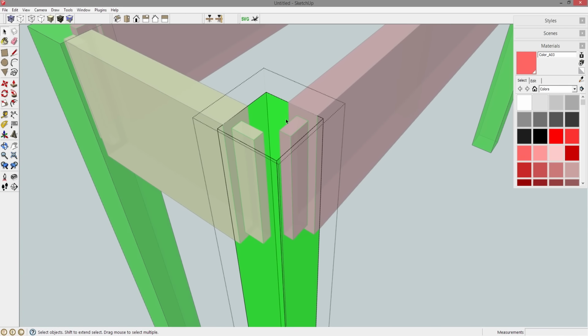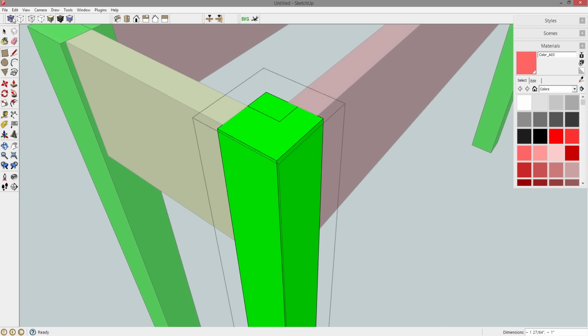Now if I need to draw on this back face, but in this orientation the top face of the leg is in the way. So if I press R for rectangle and start drawing, I'm not drawing on that back face back there. As you can see, I just drew it on the top side of the leg, as confirmed there. Press Ctrl Z to back up.